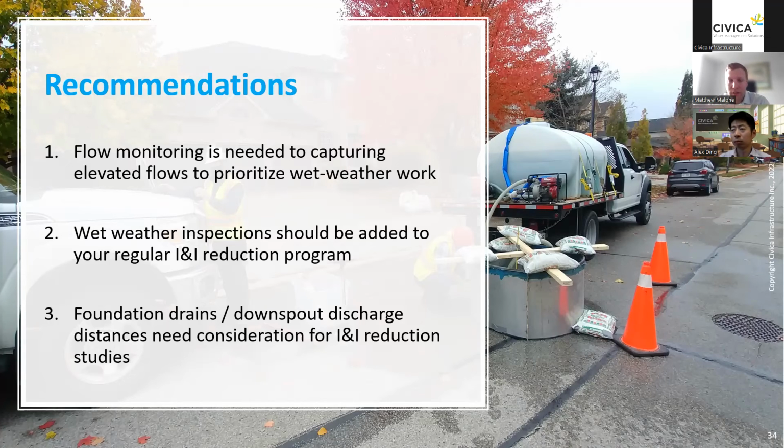If you have good flow data and you have certain assets that might be underwater during storm events, or you may suspect, or if you have foundation drains, or other features that the pipes or maintenance holes are maybe not in the best condition, and you want to see what's happening during these storms, it's certainly something that should be part of the overall I&I inspection and reduction program.